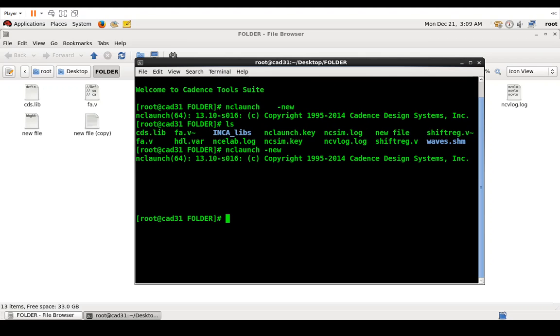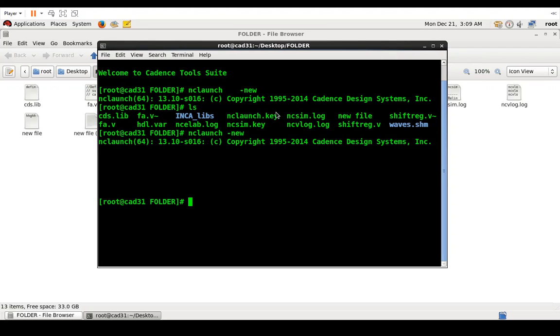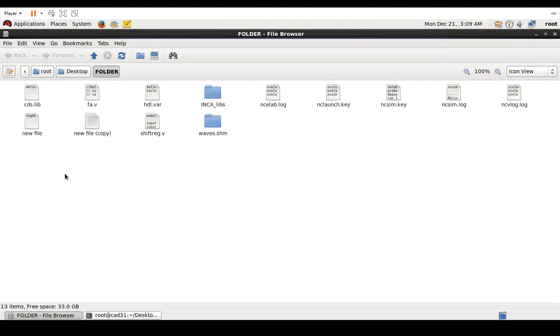Good evening. So we will continue with the synthesis steps where we have the designs and we want to generate the power, area and timing reports and the netlist. So basically we are doing the front end VLSI design where we want to convert this into a netlist which eventually will go for back end VLSI design where the floor planning, layout, placement, all that will happen.